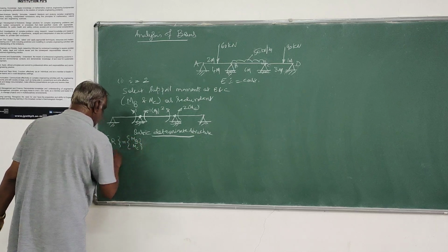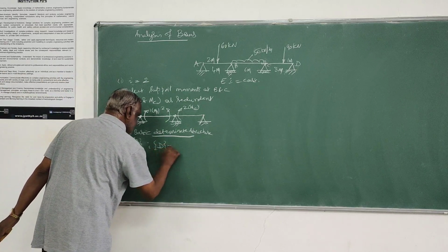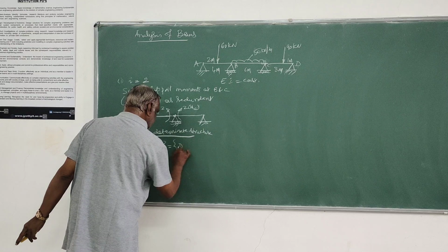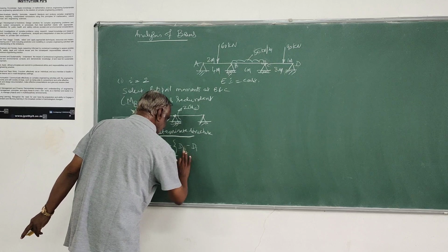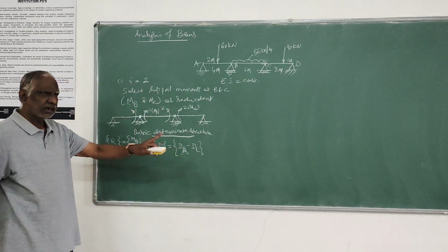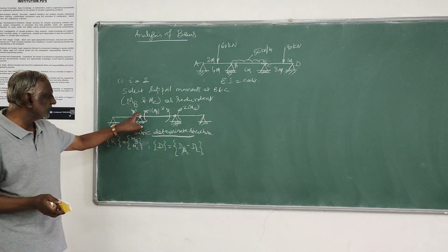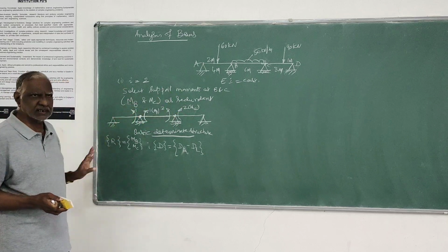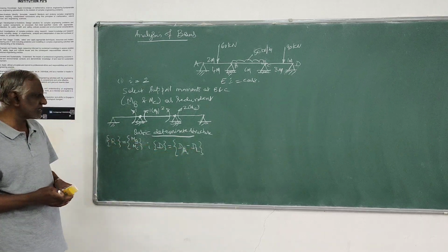You can generate this matrix R, and also you can generate the displacement corresponding to these redundant coordinates, which is nothing but DL minus DR, DR minus DL. DR is the support settlement, if at all it is given, and DL is the displacement which occurs on account of these loads along these redundants. Along these redundants, we limit the release, so it is free to undergo displacement. That displacement we call DL.